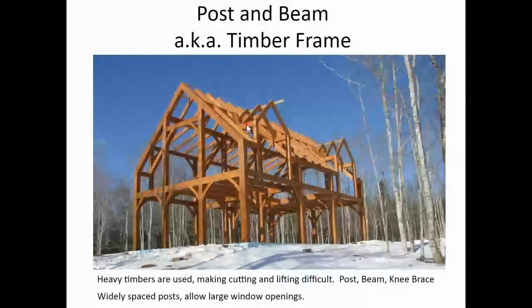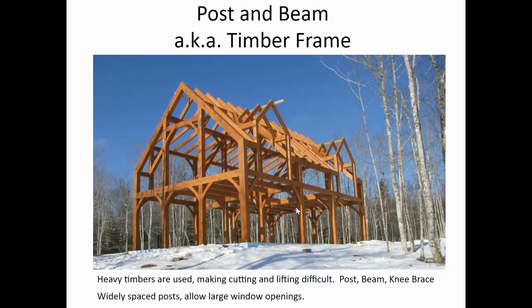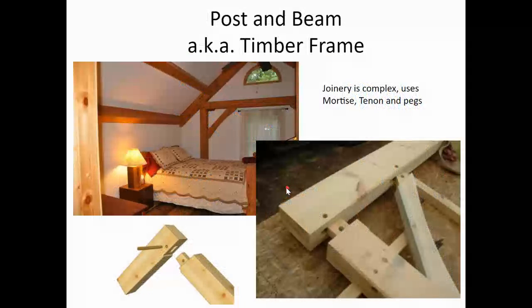This is what we call post and beam, otherwise known as a timber frame. Again, we've got big, heavy pieces of not lumber, but timber. This is the post. This is a beam. This is a brace. Again, going to need a crane to pick this up, or lots and lots of people, and you need specialized tools to work with this.